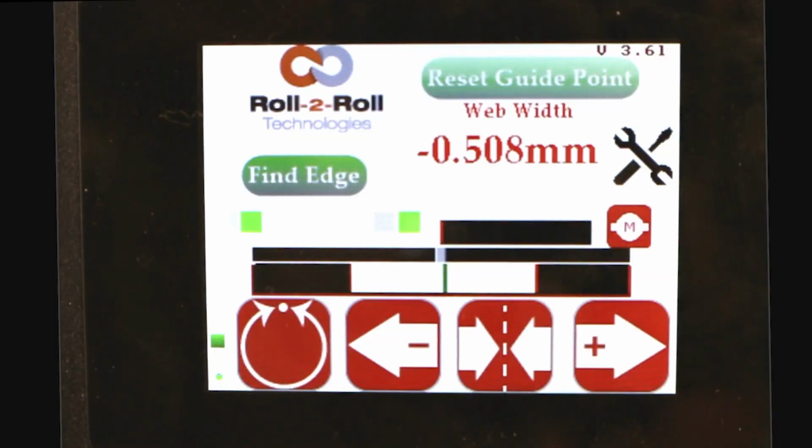Even though we prefer to provide a digital output, the analog output option is available so that you can connect to a legacy system where you have just a way of logging the data into your PLC, if your PLC is old and it doesn't have the Ethernet communication option. Let's go over that in detail again.